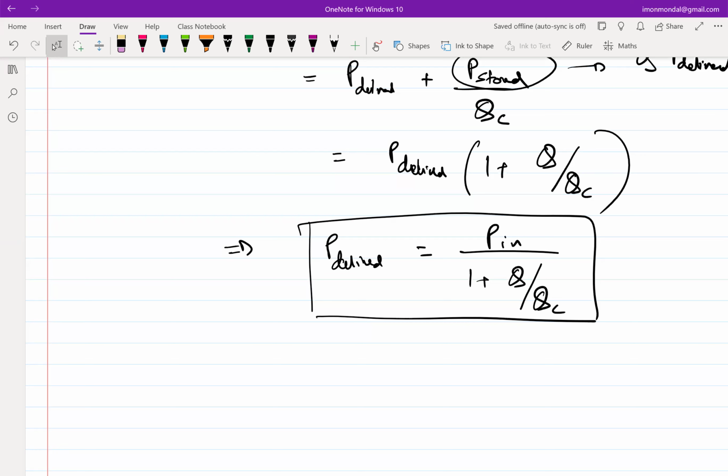And this typically is referred to as insertion loss. When you take up a data sheet of any RF system, you will see one plot of insertion loss. That insertion loss will tell you how much loss you have in the network. Okay. In the next class, we'll see given certain amount of insertion loss, what you can do to optimize for the loss. What can you do to optimize the loss? Okay. Thank you.